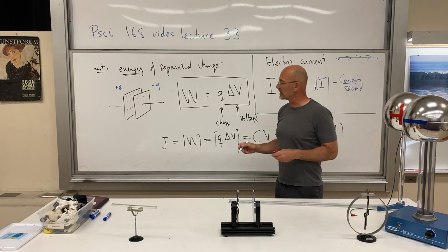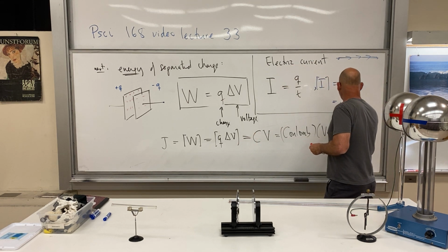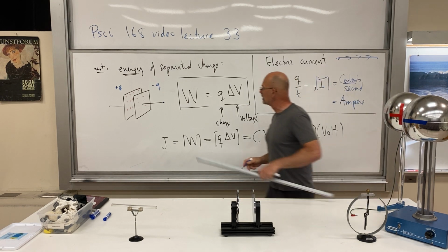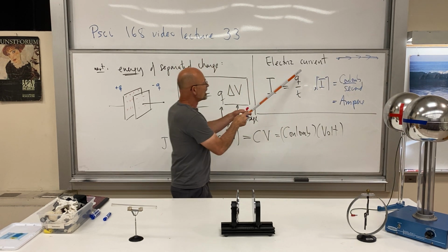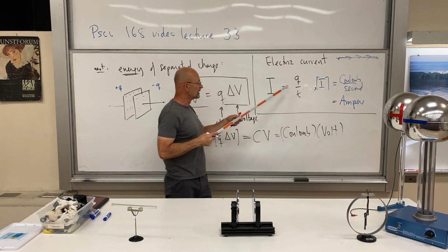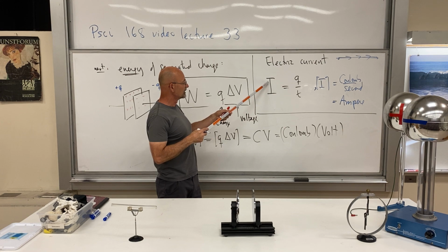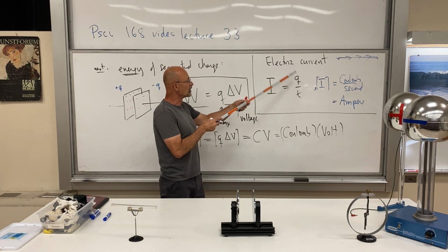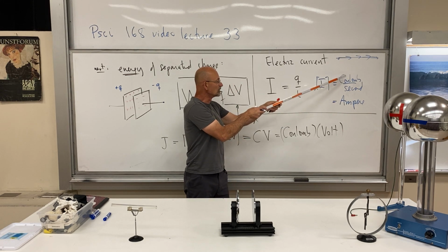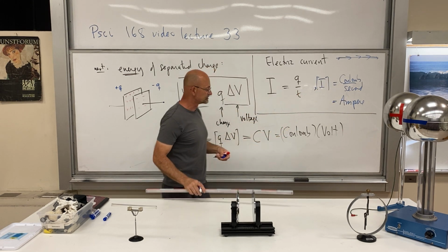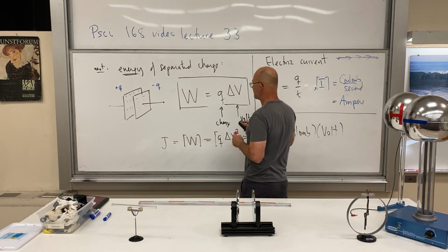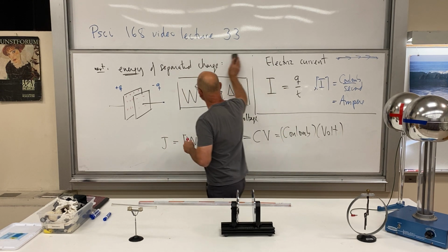It's called the ampere. So you could say 1 coulomb flows along the wire in 1 second, and that would be 1 ampere. So current is charge per time flowing past some point along the wire, and a coulomb per second is an ampere. Good, so now I can talk about the power explicitly.